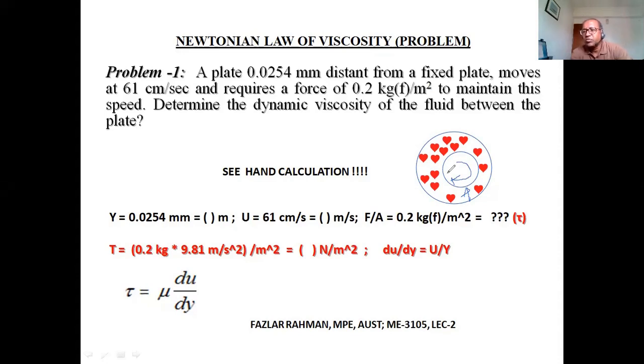But if you use the wrong fluid, if you use a fluid with very high viscosity, then what will happen? Then the rotating parts will not move perfectly because you need higher force to rotate the parts. Again, if the density or viscosity is very low, then what will happen? The fluid will not stick between the two surfaces. Then this shaft will ultimately, during rotation, touch the bottom surface and it will damage your shaft and damage your ring or bearing.